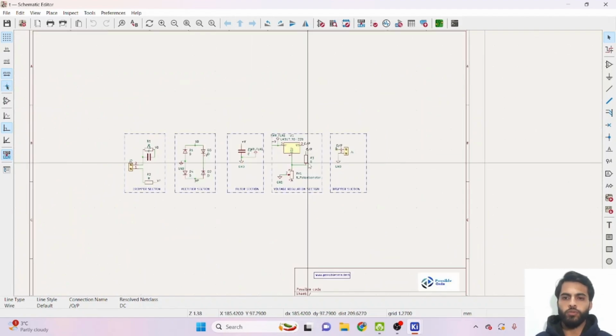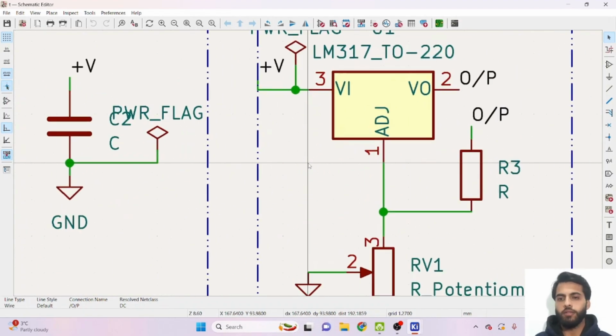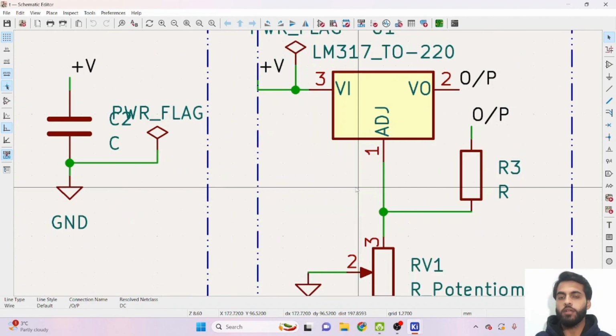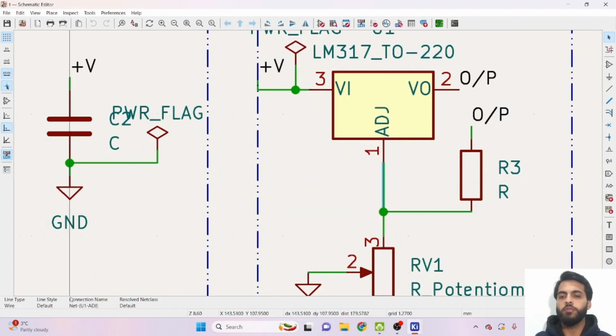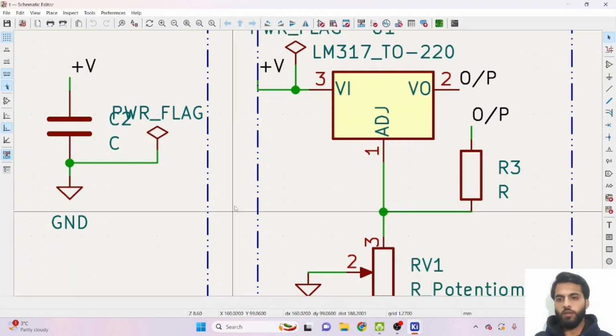There appears to be a small issue now. Only the connections with net name have been assigned a net class. But what about the connections which have no net name? For example, this connection. Its net name is default. It doesn't have any net name. So how can we assign? If I try to assign a net class to it, let me see. Seems like I can't assign net class to it.